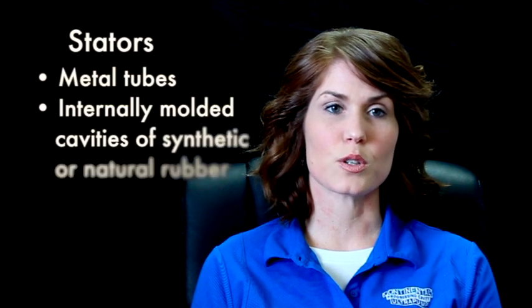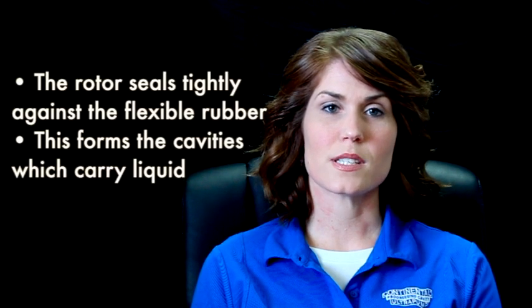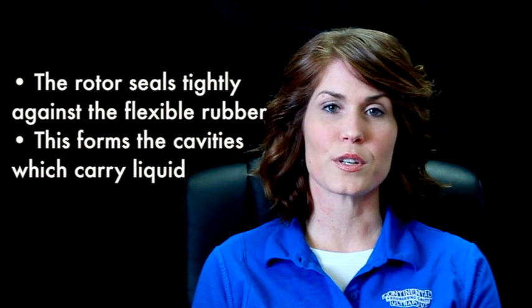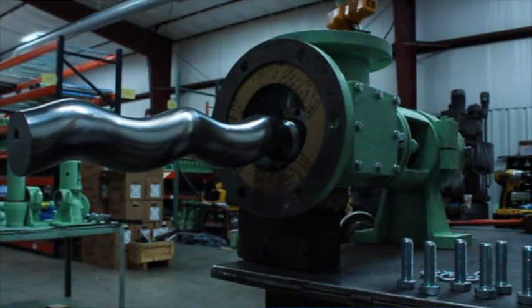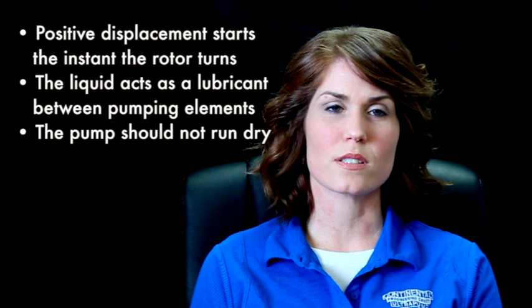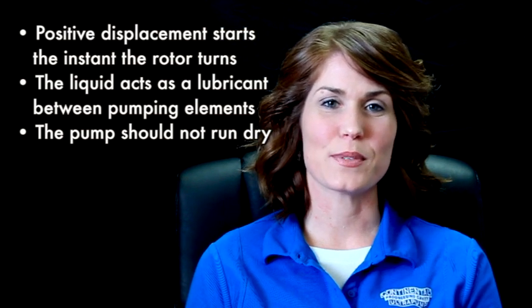The stators are metal tubes with internally molded cavities of either synthetic or natural rubber. The rotor seals tightly against the flexible rubber inside of the stator as it rotates, forming tightly sealed cavities which carry the liquid towards the discharge port. The liquid does not change in shape or size when pumped due to the tightly sealed cavities. The effect of the progressive cavity design is that the fluid is moved at a very predictable and steady rate. Positive displacement of the pump starts the instant the rotor turns. The liquid acts as a lubricant between the pumping elements and the pump should not run dry.